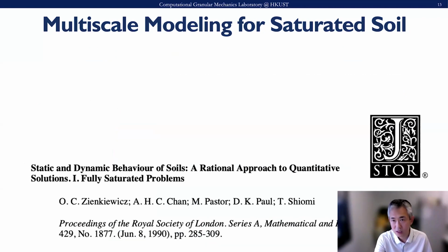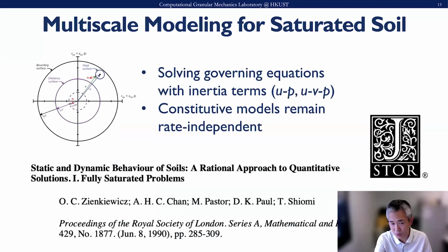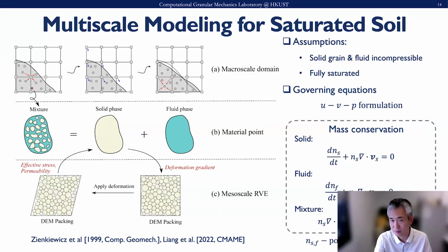So for the saturated soil case, we use this UP formulation we mentioned before, and we use Terzaghi's principle. Here we assume that the solid grain and fluid are incompressible. For each material point, we consider a mixture of the DEM solid phase with a fluid phase. For the solid phase, we use the DEM to simulate it and use Terzaghi's effective stress principle to extract the effective stress, as I mentioned.